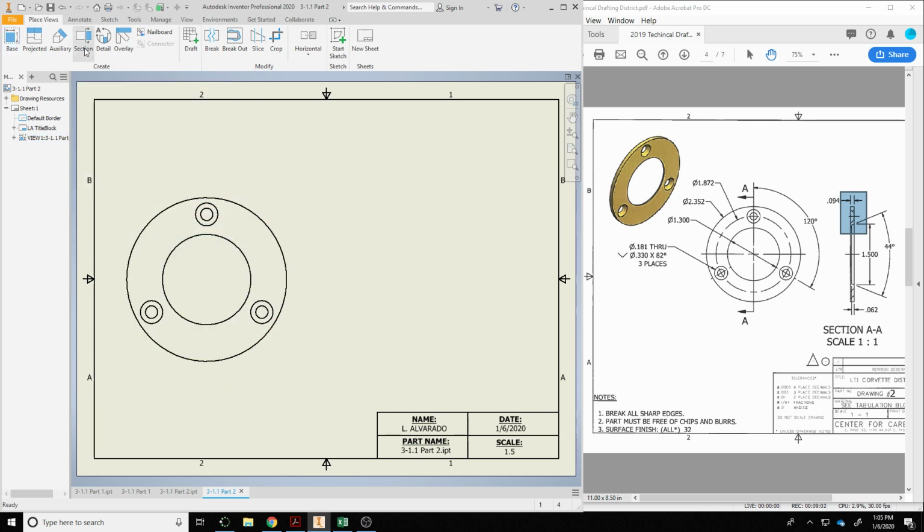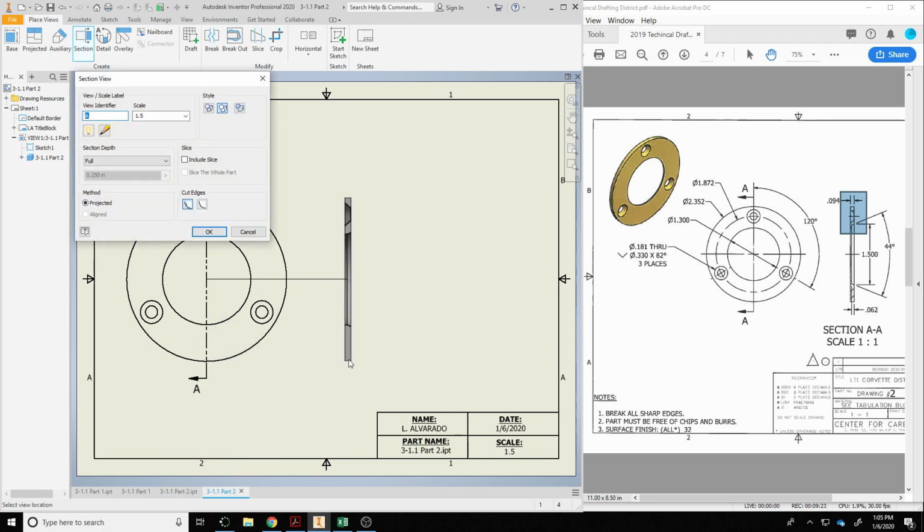And then I'm going to make a section view. So I'm going to hover, put my mouse right there, move my cursor straight up, directly above, and then move it all the way through. I'm not stopping on this point right there. I'm moving straight through the part, right clicking and clicking on continue, moving out. I'm going to click on this little light bulb and turn it off.